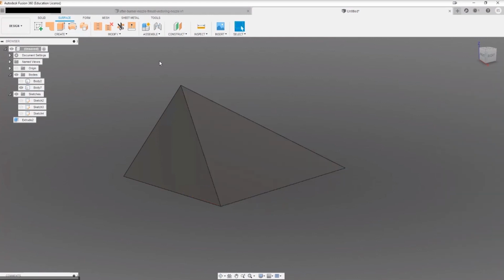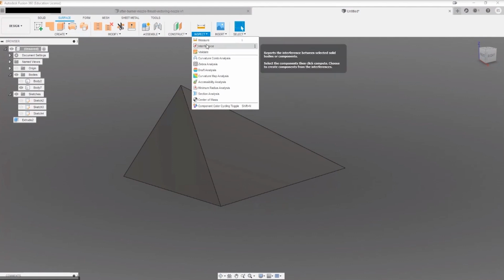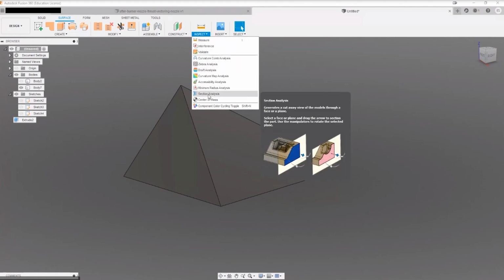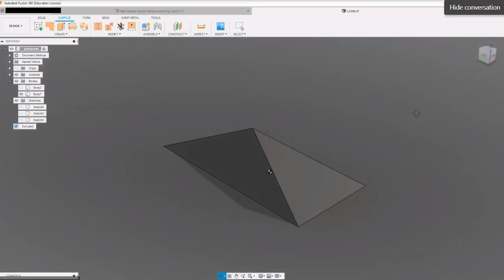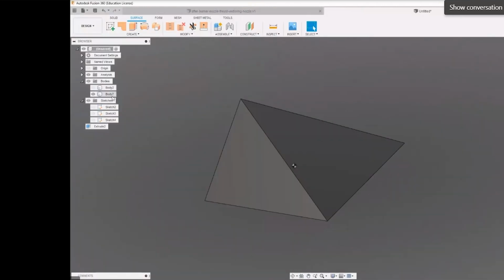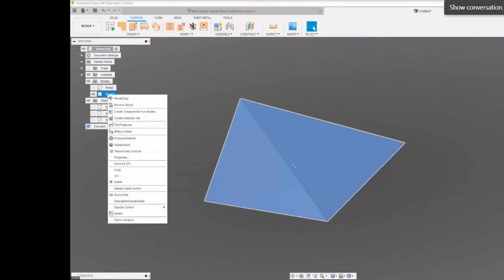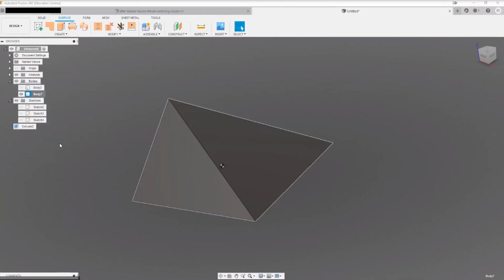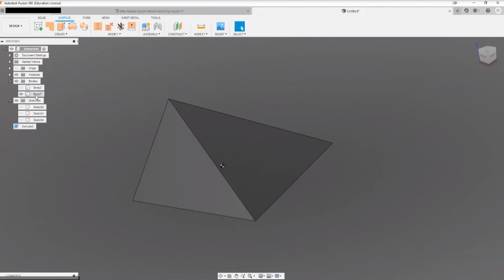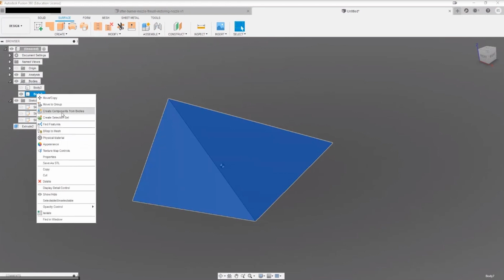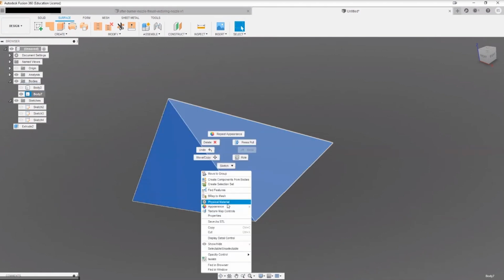Okay. And then you've got another really nice one that we like to use quite a lot. Yeah, center of mass. Remember, I mentioned that at the start. So that's one of the analysis tools that you can do. Now, if we want to take a look at the weight of it, you can select the body, go to, you can change the appearance actually as well. There's all kinds of different materials, but that's more for presentation. If we go down through to here, there's going to be material properties somewhere, no. Okay, here, physical material.